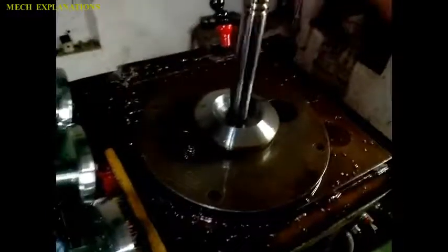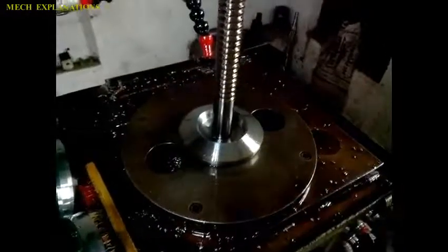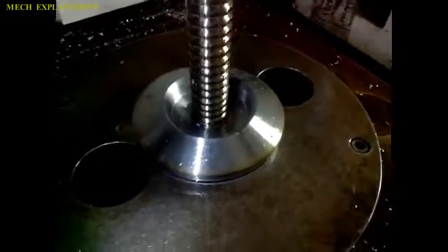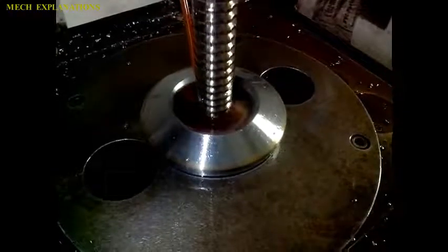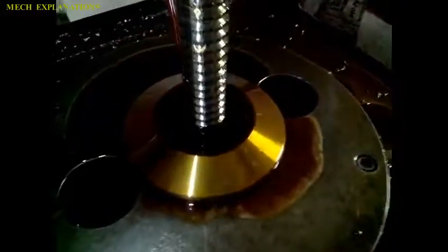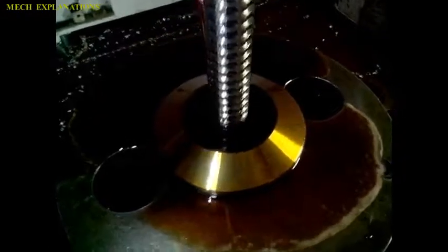In both processes the cut is performed in one pass of the broach, which makes it very efficient. Broaching is used when precision machining is required, especially for odd shapes. Commonly machined surfaces include circular and non-circular holes, splines, keyways, and flat surfaces.